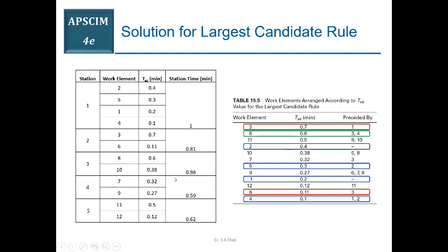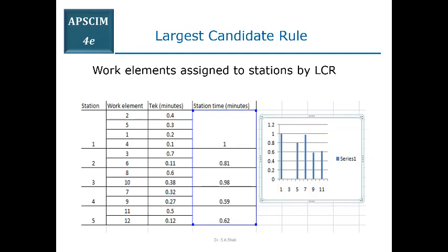But actually when you take into consideration the precedence requirements, the sequence that must be adopted, and the available time slot which is 1 minute, based on that the actual solution for the actual scenario is 5 workers, or you can say 5 workstations within that system. So once you come up with the balanced solution, which is this one,